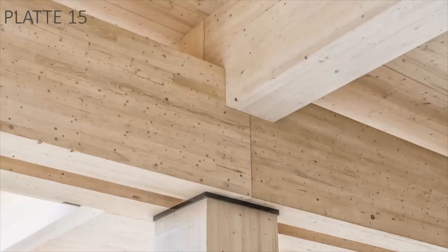We also tried to make the connection of the girder to the column simple, also a bearing connection. The wood column actually continues all the way up through, but it's held back to make room for the girder connection here. There's a bearing plate that just fits around that internal column. You can see a couple of screws here, pretty hard to see, and there's a couple more up at the top. Very simple, fast to erect.